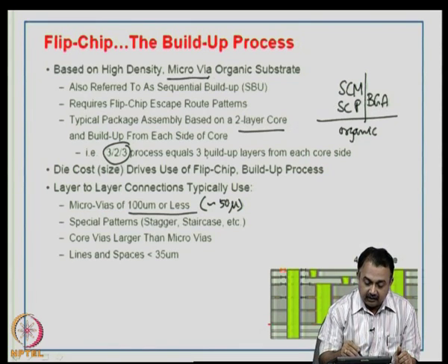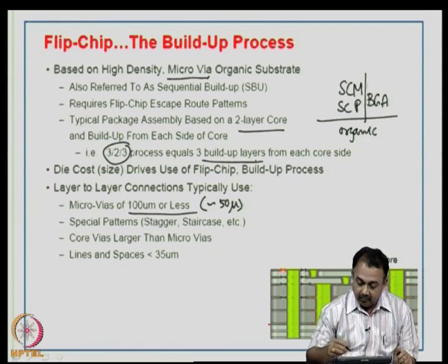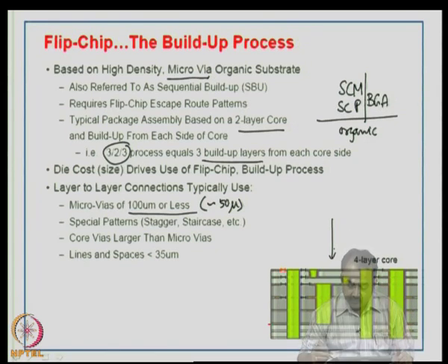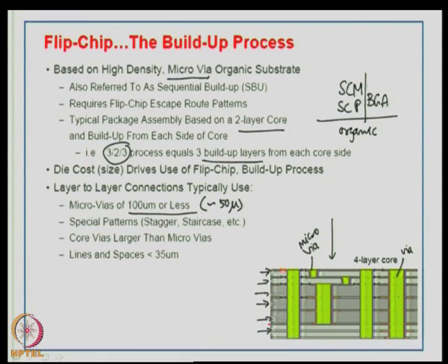We will talk about build up layers when we come to PWB technologies, but if you look at this figure here in this particular slide, you will see that there are a number of layers of conductors, typically representing PWB structures. These are built on organic substrates, and this is a via which connects 2 metallic layers. This is also a via, but this could be a micro via because it is built in a sequentially built up pattern methodology, whereas this can be a through hole structure. Okay.